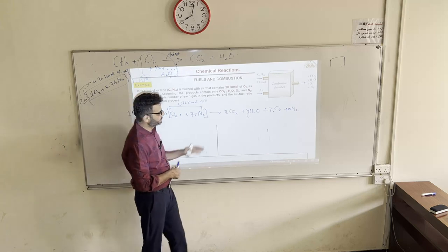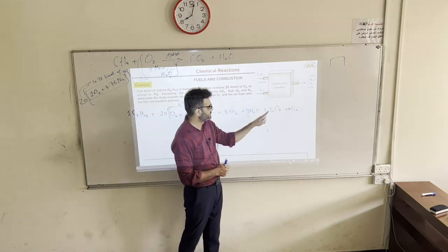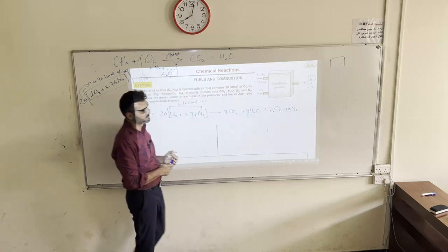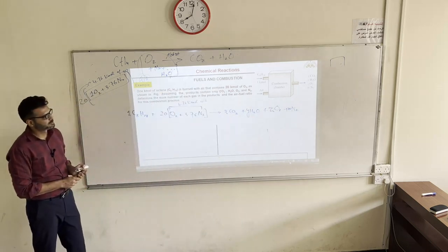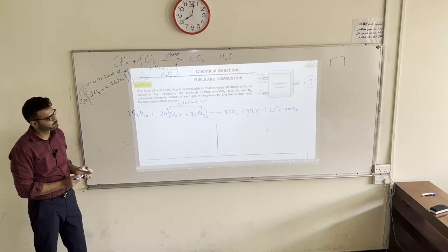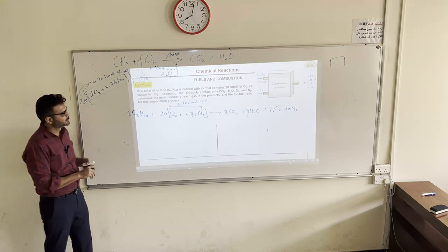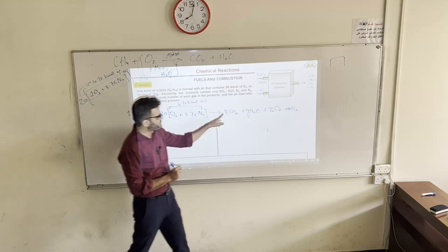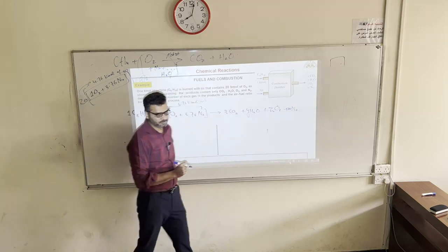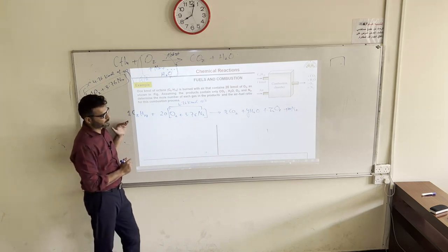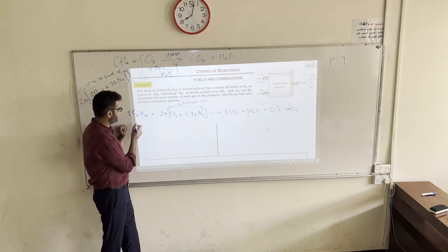So they found out from these exhaust gases there is also pure oxygen. Now we can find out the number of moles of each of these. Nitrogen will be the same. So we need to find out these X, Y, Z, and W, moles of these exhaust gases. So it is by mass balance. So let's start with carbon.